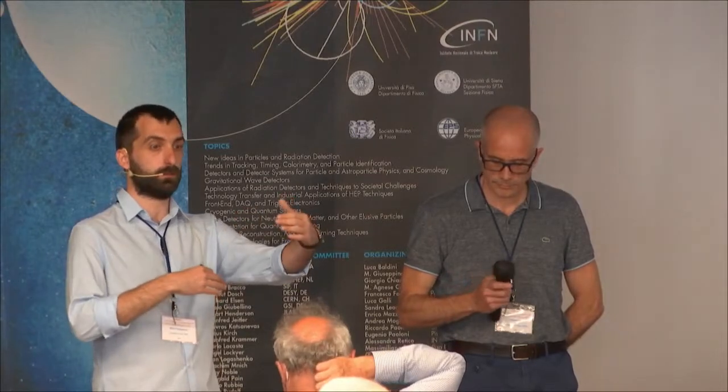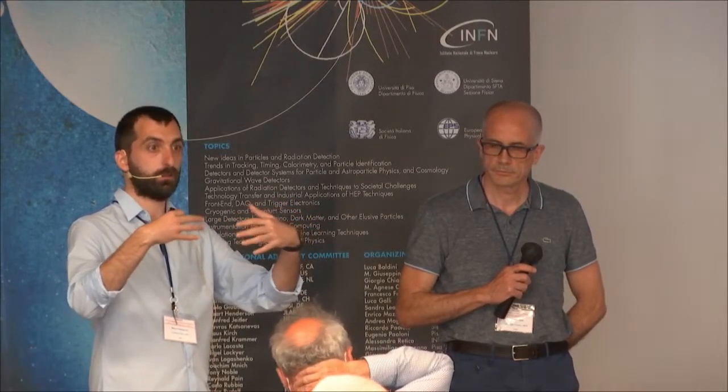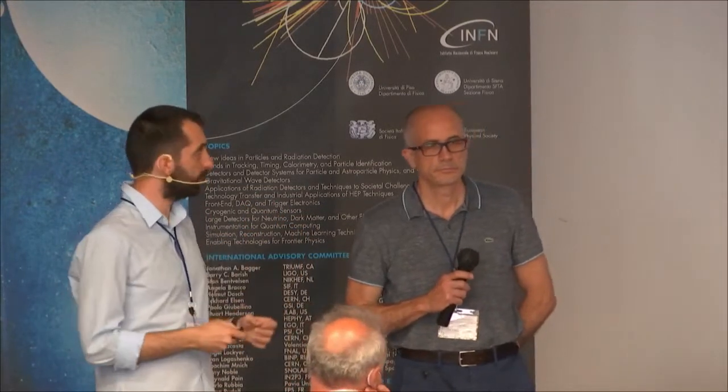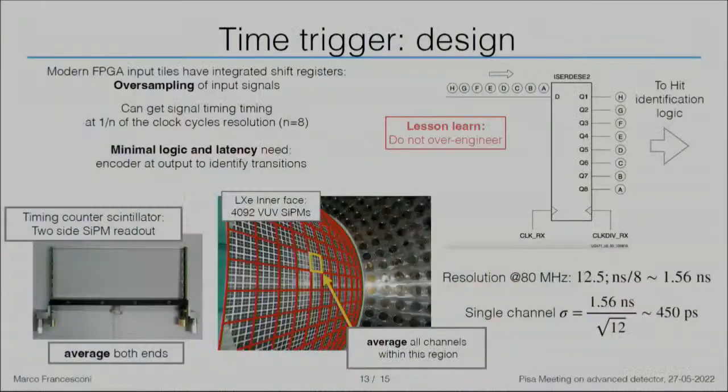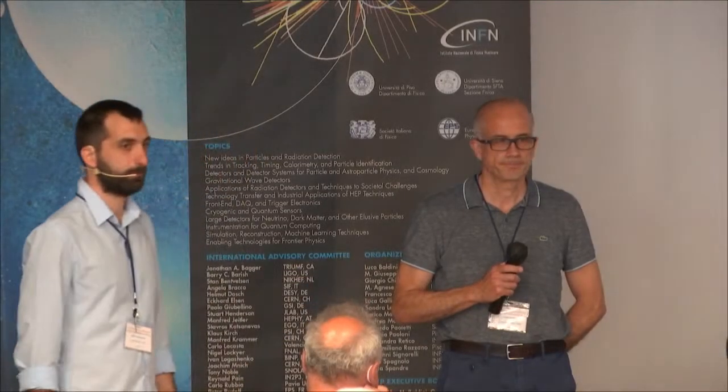The deeper the energy deposit is, the more spread is the energy in the interface, the lower is the amplitude, the worse is the time. What we plan to do is to use the PMTs, which have a much faster rise time, and therefore should help in reducing the time walk. Essentially, we have a leading edge discriminator, so we cannot do much more for this.